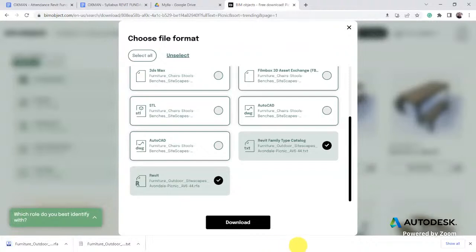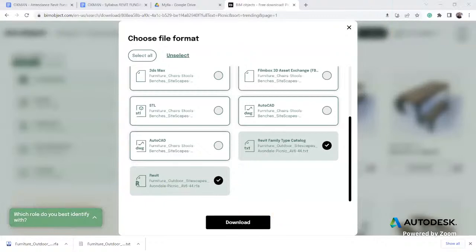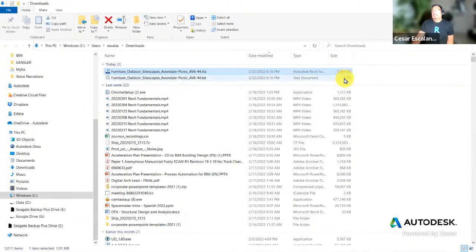Do you have to be careful of how large these files are? Yes, and so before we load them, we want to open show in folder and see how big the files are. In this case, a typical family goes between 600 and maybe 2,000 kilobytes. Anything that is bigger than 2,500 is borderline. But anything that goes bigger than that is something we need to be careful about. In particular, it's going to be copied a lot across different spots in the project.